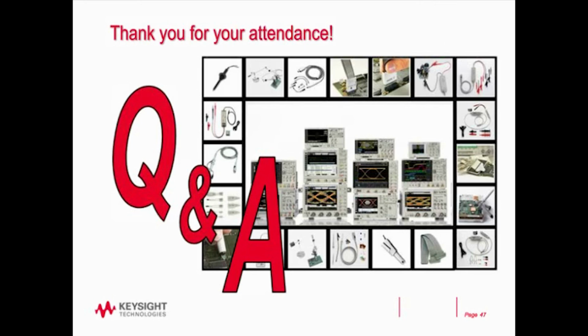About the highest bandwidth available today in a high voltage differential probe that will cover in the range of 1,000 volts is about 200 megahertz. And so right there, you've limited the measurement bandwidth of your system to the bandwidth of the probe. So it doesn't make a whole lot of sense getting a multi-gigahertz scope to measure something with a couple hundred megahertz probe.